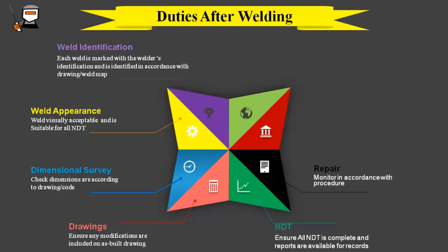Repair. A weld defect to be repaired shall be removed to sound weld metal. Repair weld shall be made using a qualified welding procedure. Repair weld shall be made by a qualified welder or welding operator. Preheating and heat treatment shall be as required for the original welding. Post-weld heat treatment. The post-weld heat treatment to be used after production welding shall be specified in the WPS and shall be used in qualifying the welding procedure. Heating and cooling method will be mentioned in the WPS. Heating and cooling rate per hour according to thickness will also be specified on the WPS.